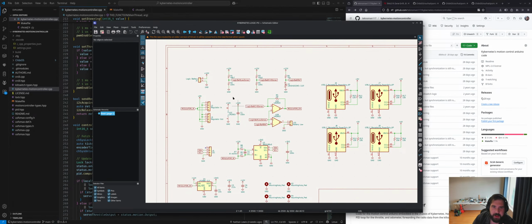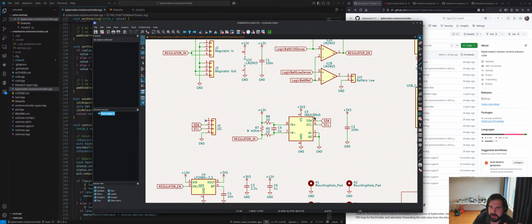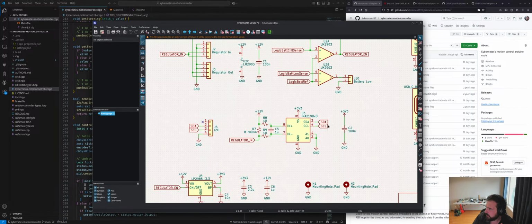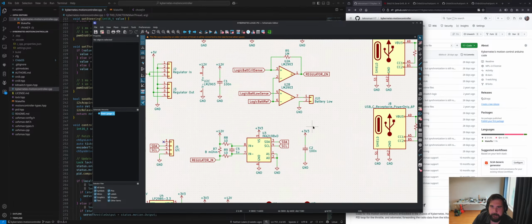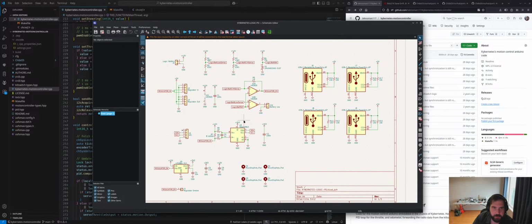And then that 12 volts thereabouts coming in from the battery is then sent through this current sense resistor here on the regulator in. This is an INA219B current power voltage sensor. It's connected over I2C to the chassis microcontroller. And then that 12 volts is then run through.